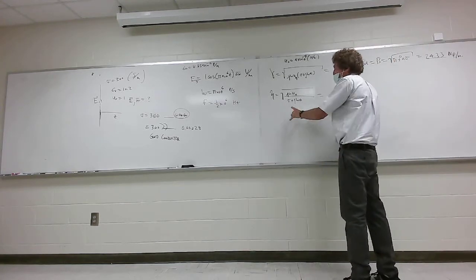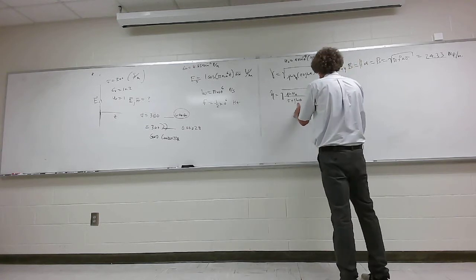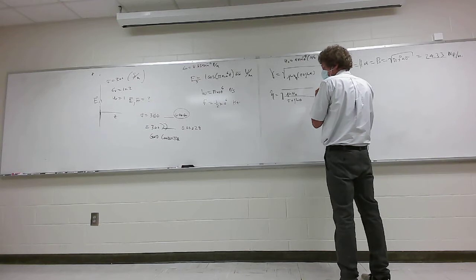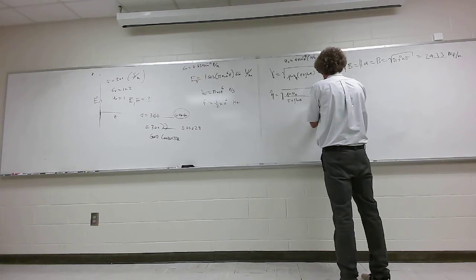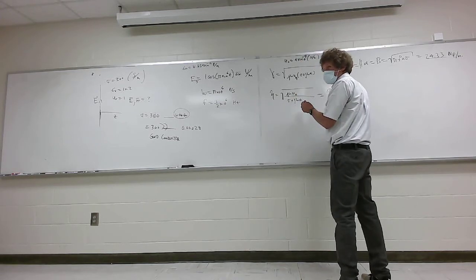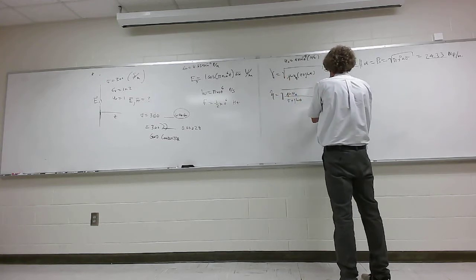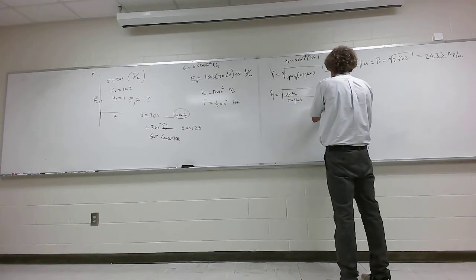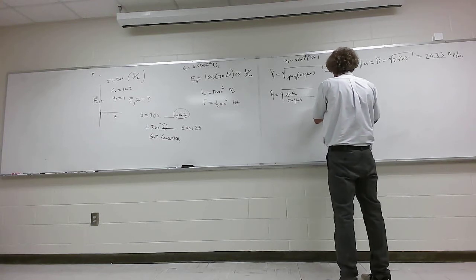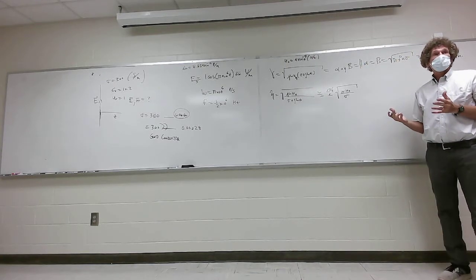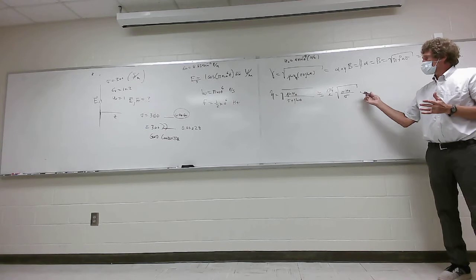Now, if that's the case, let's get this one too. And by the way, since sigma is so much greater than this, we can just say this is what? That's square root of j, which is really e to the j 45 degrees, or j pi over 4, because j is 1 at an angle, e to the j pi over 2. Do you remember this from last time? Square root of that is e to the j pi over 4. And then it's going to be times square root of omega mu 0 over sigma, right? If it's a good conductor, because sigma is so much greater than omega epsilon. Do y'all agree with this, class? What do you get for this?